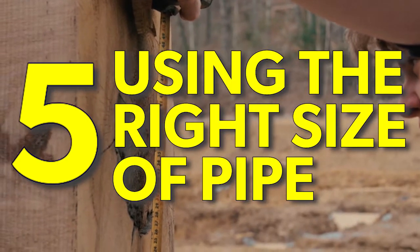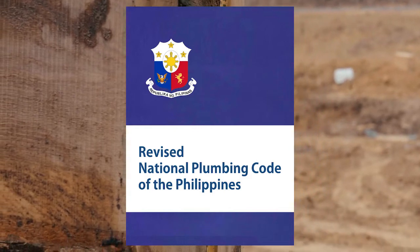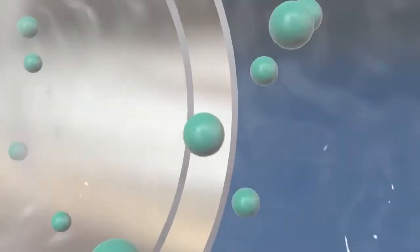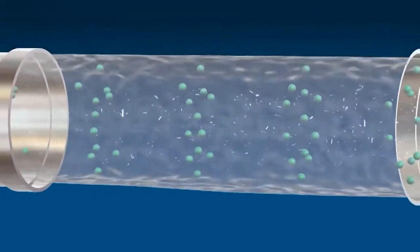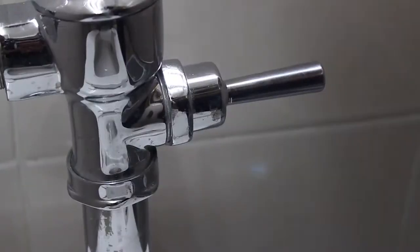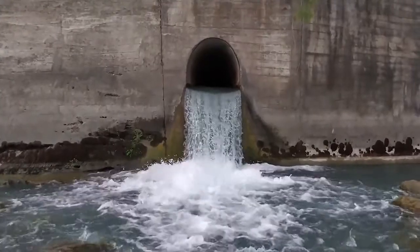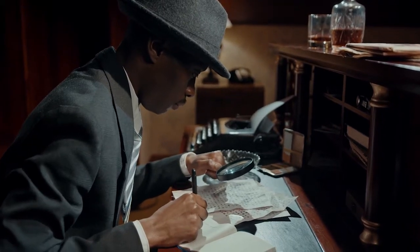5. Using the right size of pipe. According to the National Plumbing Code, the size of the waste pipe intended to receive waste from the fixture must be of sufficient diameter, adequate enough to accommodate the velocity of flow, making it as nearly scouring as necessary, flushing or washing out dirt or grease by flowing through to prevent the silting of the pipe. Service efficiency, nevertheless, was believed to increase with the larger pipe, which unfortunately triggered disagreement among people in the plumbing industry as it holds no scientific evidence.